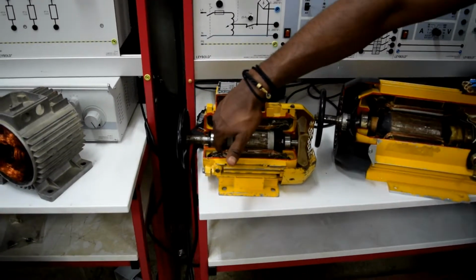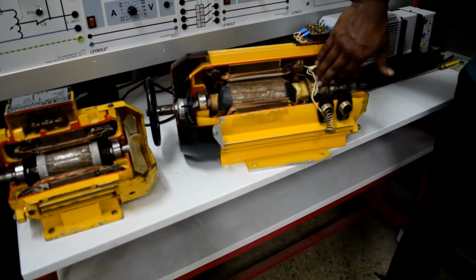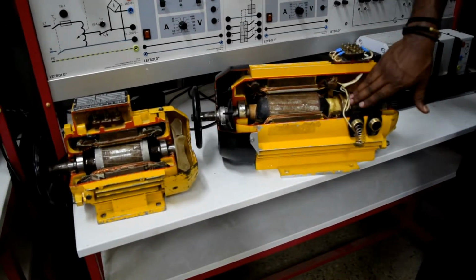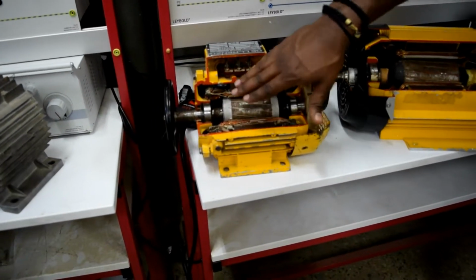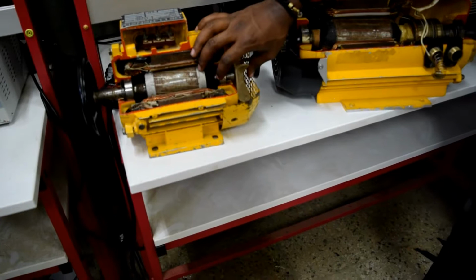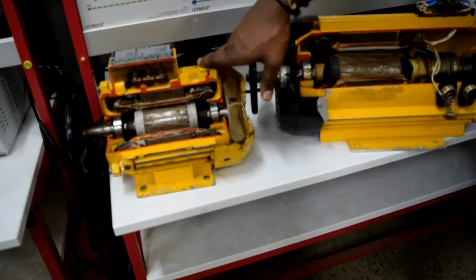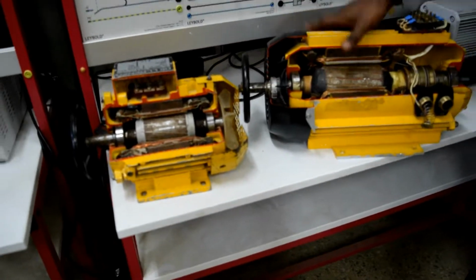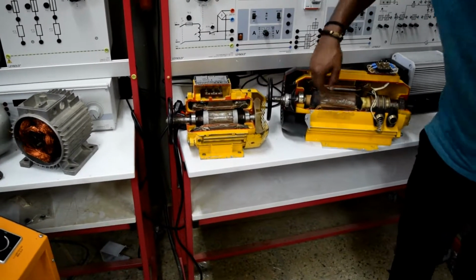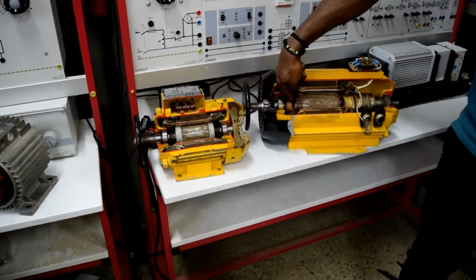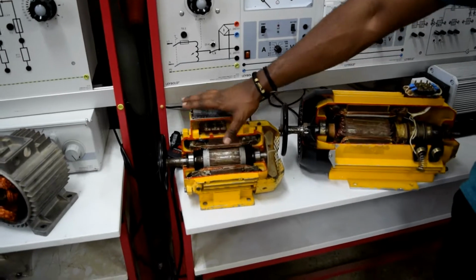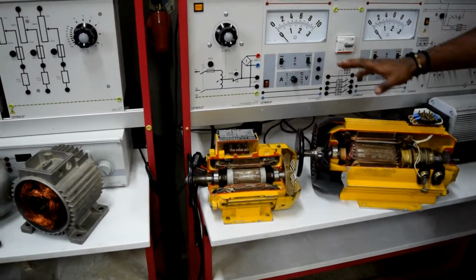As you see it here, there is a better space factor than this one, because there is a slip ring here and the brushes, so the space is occupied by those things. But here there is no brush and slip ring, so there is a better space factor here. And also it has bearing rings and large space for fans, and the cooling condition is better than the phase wound one. So it has a smaller rotor overhang. As you see it here, there is a smaller rotor overhang, but here we have a bigger rotor overhang compared with a squirrel-cage one. So because of those advantages, we use mostly a squirrel-cage one rather than a phase wound one.